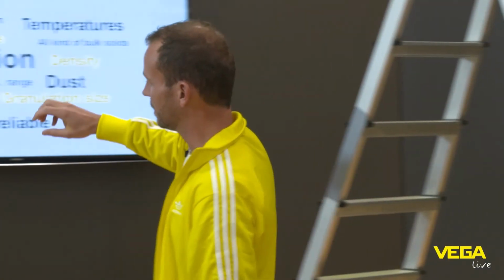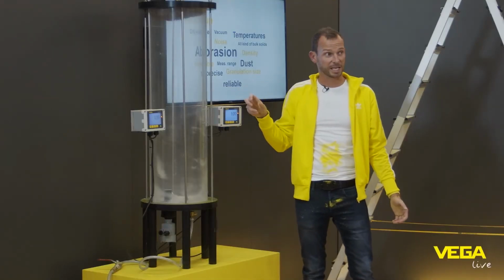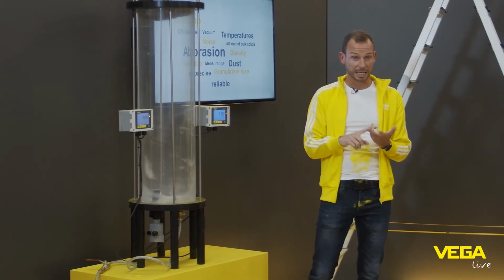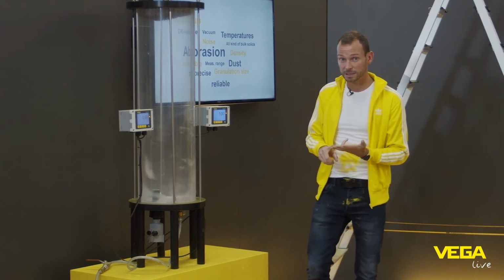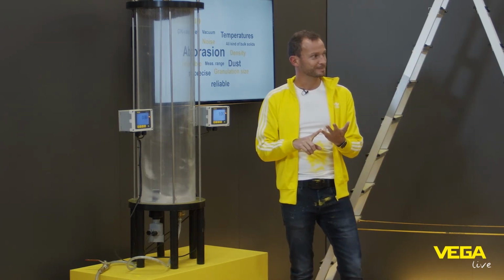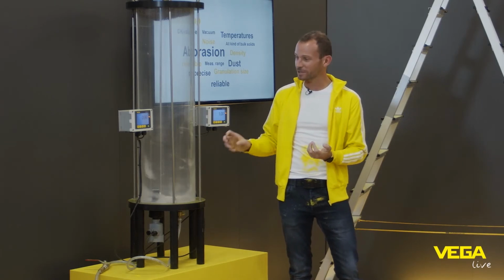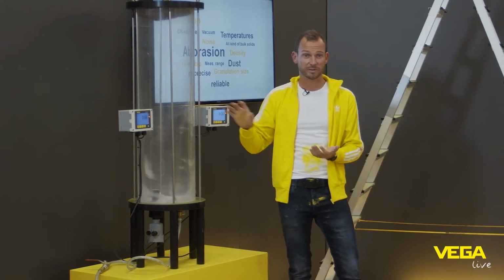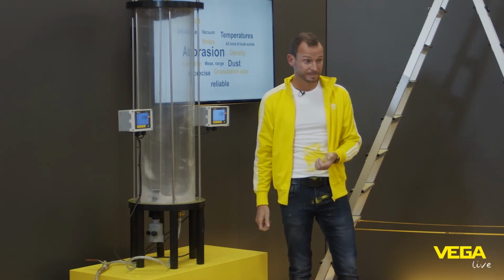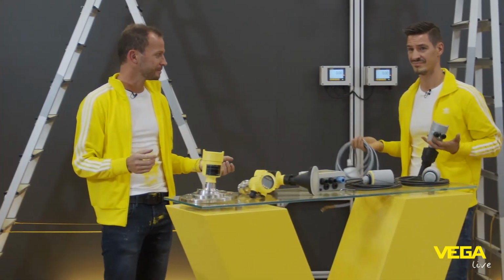And in this application here, we have seen all these influences inside of the air. Is it air pressure, air temperature? Is it dust? Is it noise? Or what was the last one? Airflow. Airflow, thank you. All this has an influence on the sound wave and has problems with ultrasonic devices. Here is also radar, more reliable. So finally, radar is the better ultrasonic.